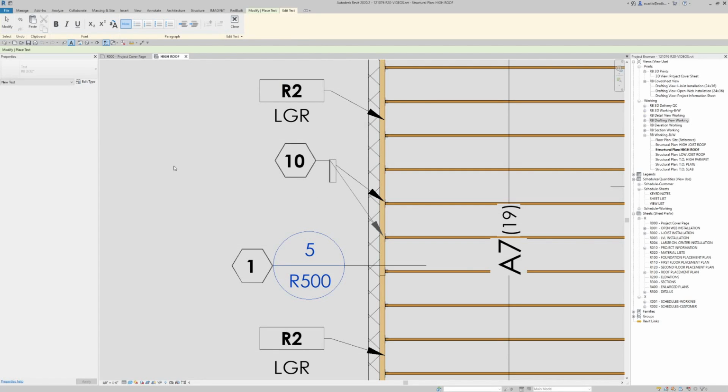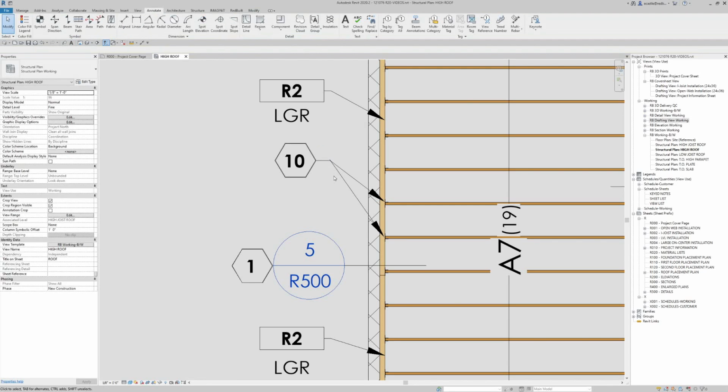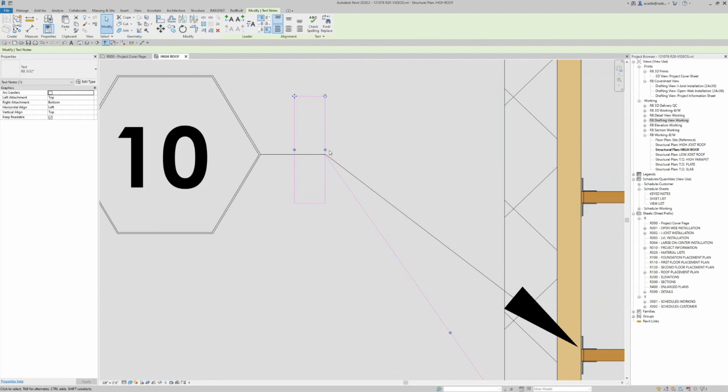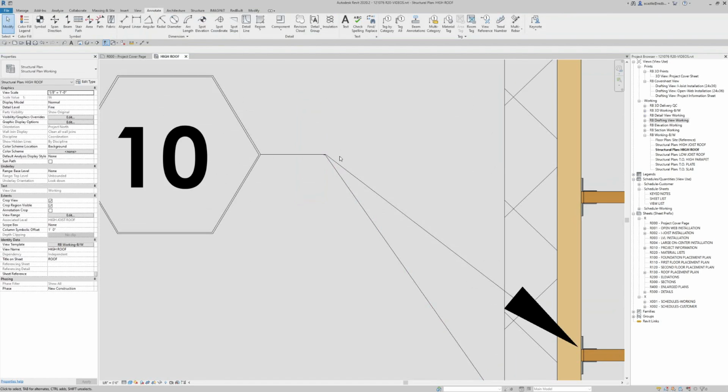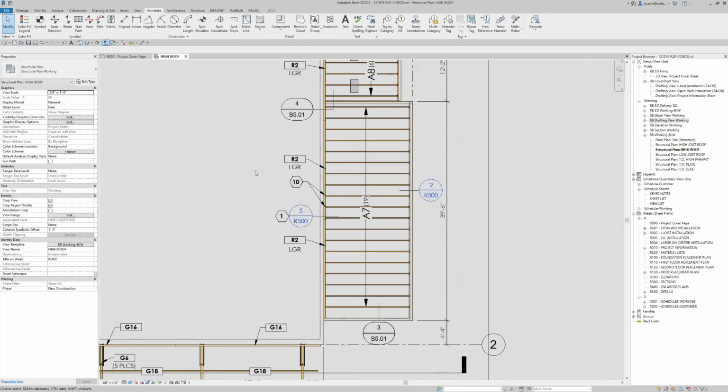Instead of any text, I'll just click outside of the box and cancel. And then I can do a little fine adjustment using the cursor keys to get it close to a line. And now we have pointing at two different hangers with one tag.